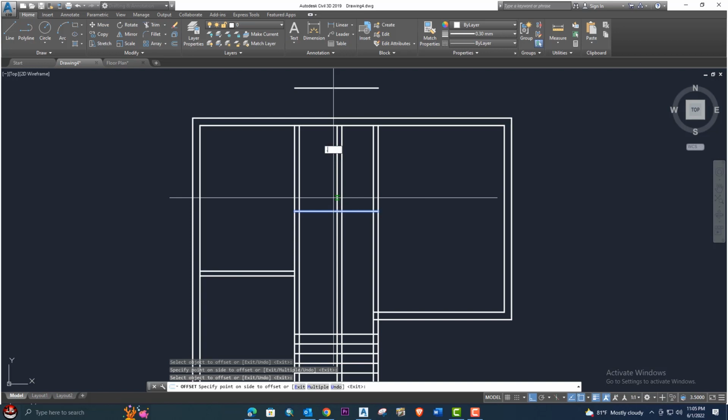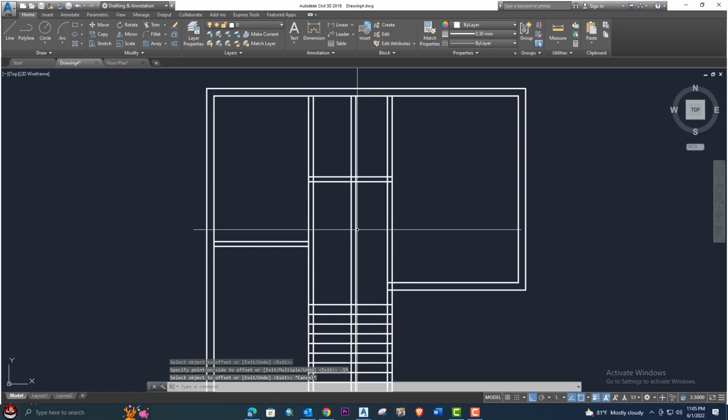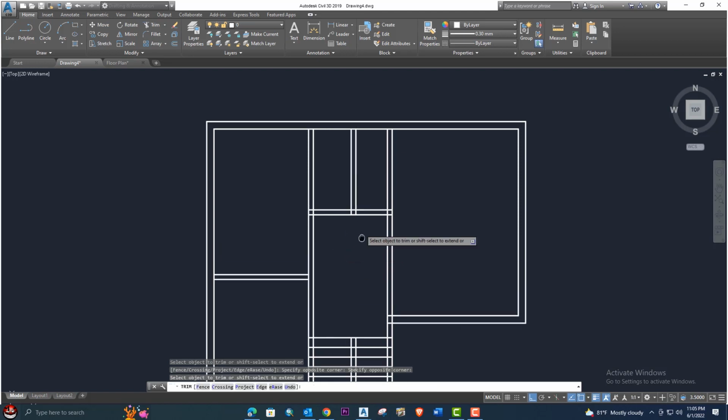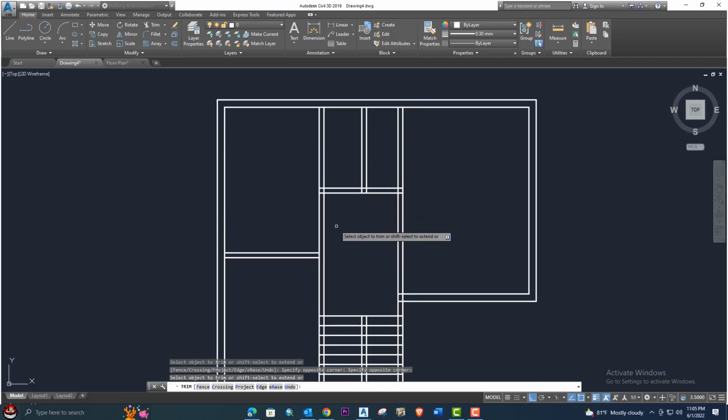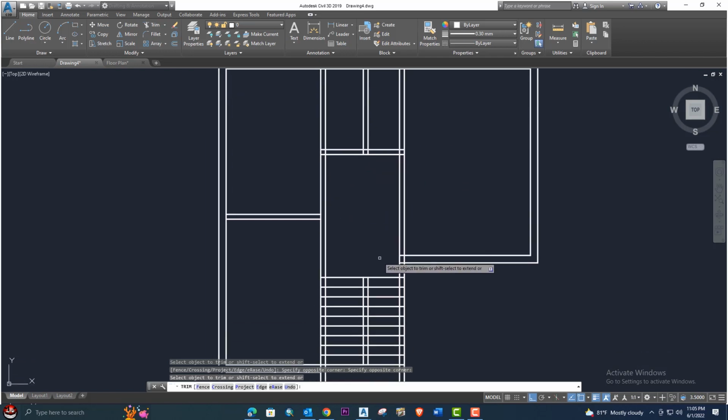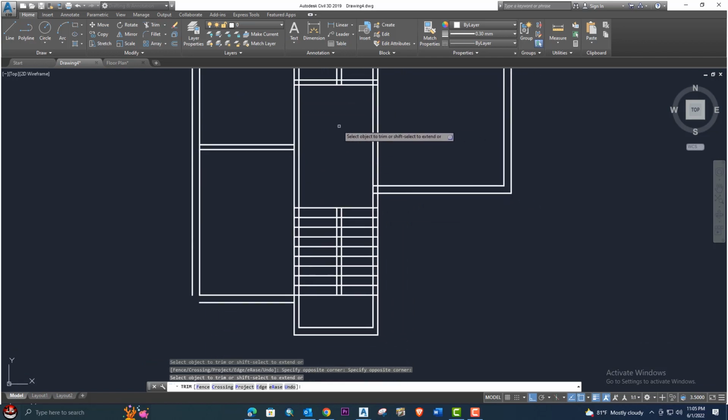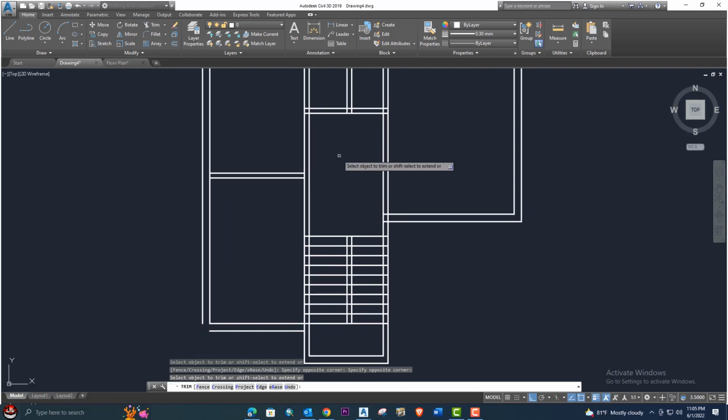And from here we need to enter the internal wall thickness 0.15, enter. Now we need to trim these lines, enter from your keyboard TR trim. Okay, enter again. So this extra line will be deleted. Definitely we need these separation walls because we have bath here and WC here. Okay, so now our lobby is already drawn.